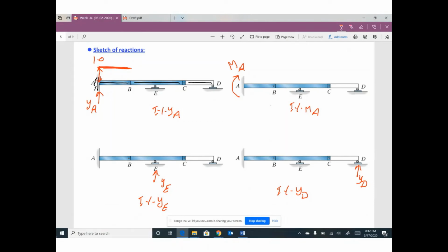This left side moved up. The right side will move up. I forget, if you pushed your fixed up by 1, this support will remain as it is, and this one will remain as it is. The new location or the new position of this part of the beam will be like this. The left side at this connection moved down, the right side will move down, so the new location of this part of the beam will be like this, positive and negative.